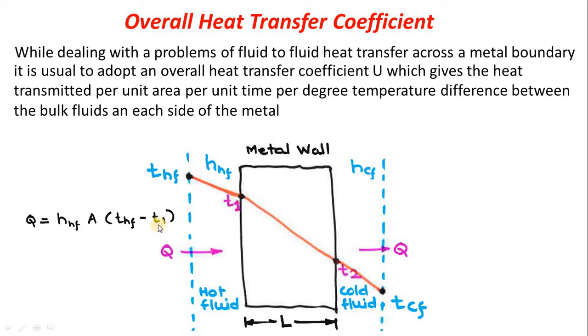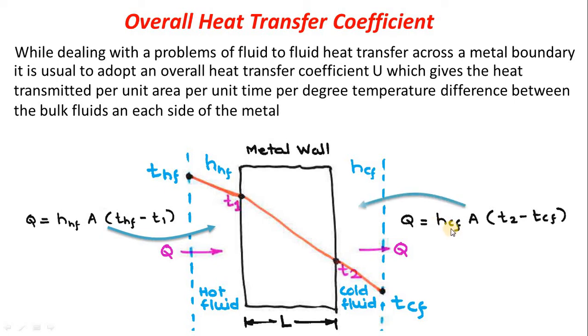At this location we can calculate the heat transfer with this formula. Similarly, you can use this formula where h_cf is the cold fluid heat transfer coefficient. For this cold fluid you can calculate the heat transfer.